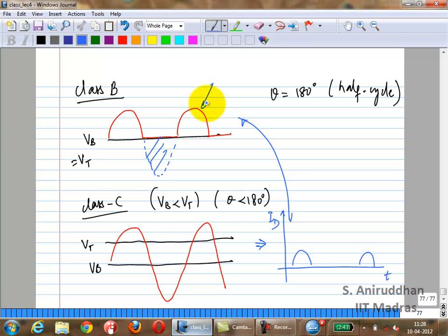Okay. So this one I have shown actually, I have shown the current, right? You have a half sinusoid, you have zero. It's cut off. Correct? If I tell you this is the current waveform, and I ask you to calculate the average value of the current. Average value is the DC current, right? Nominally the DC current. If I tell you to calculate it, will you be able to do it? Does anybody remember what this value is? 2 by pi.